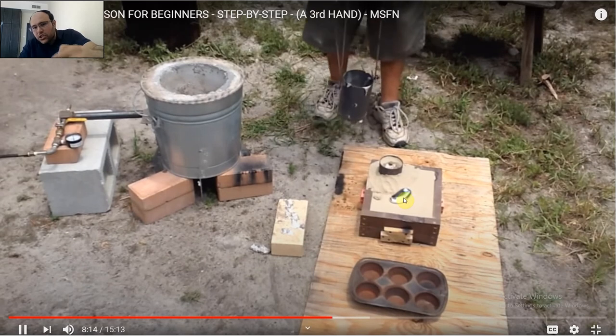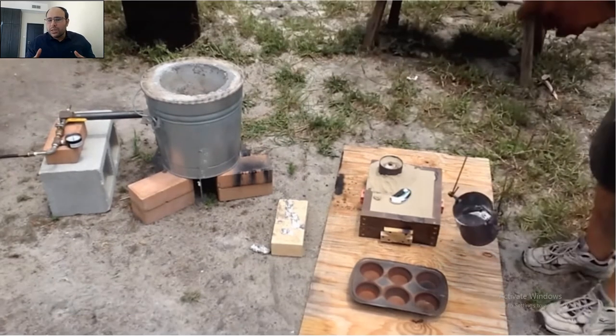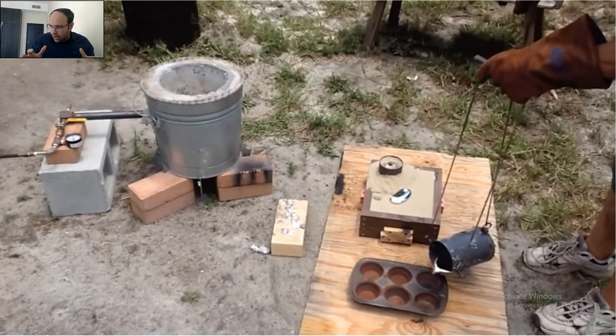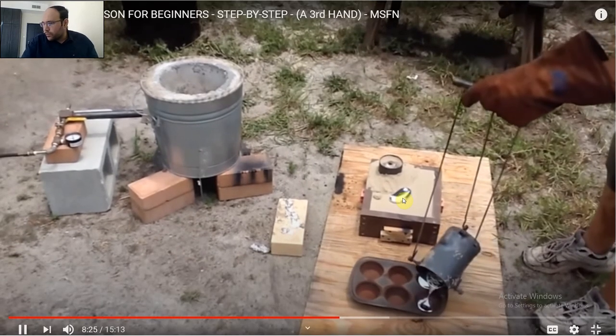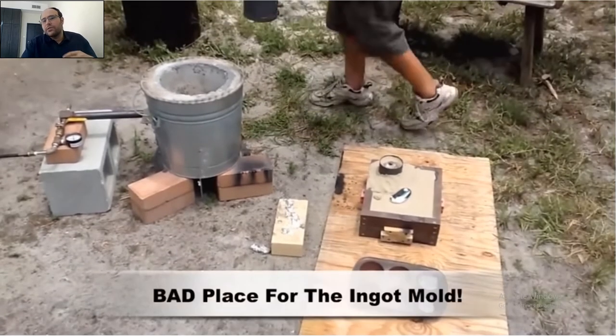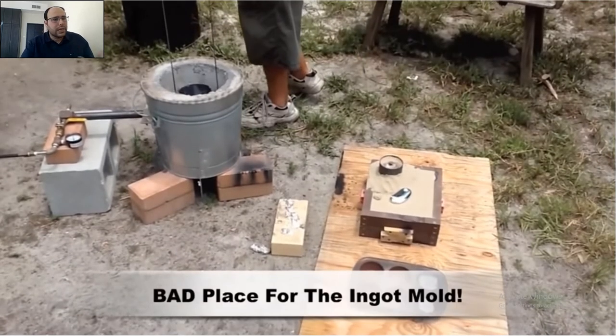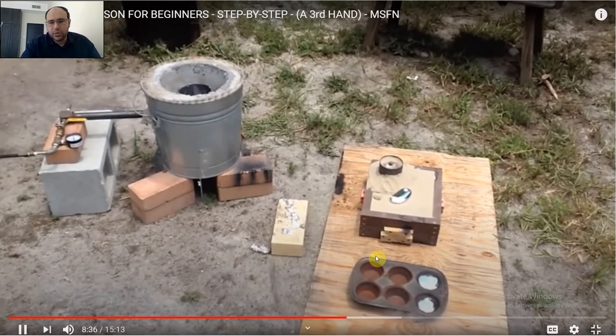As you can see, this extra material that came out from the vent indicates that the mold cavity has been completely filled with the liquid, and this extra material will then be removed. So this is one of the useful things of the vent: it gives us an indication that the mold cavity has been completely filled with the liquid. So this is the mold.